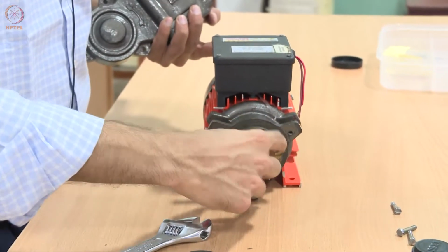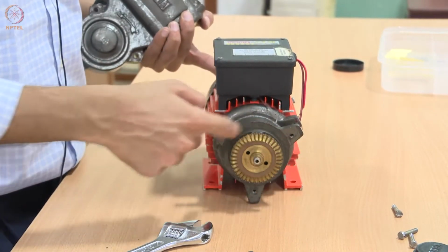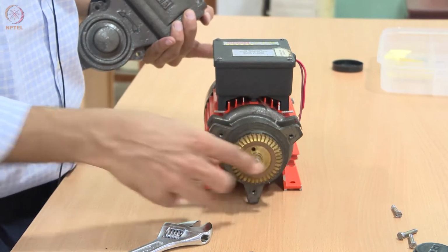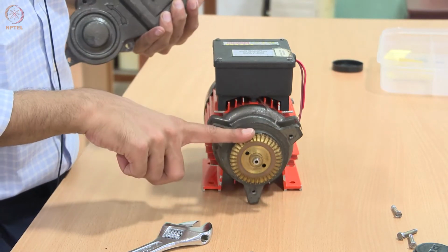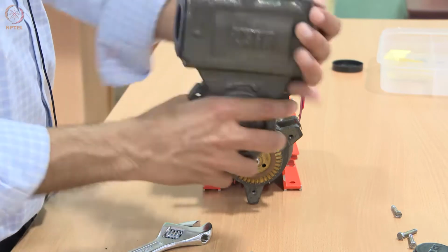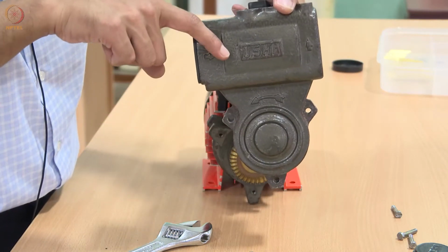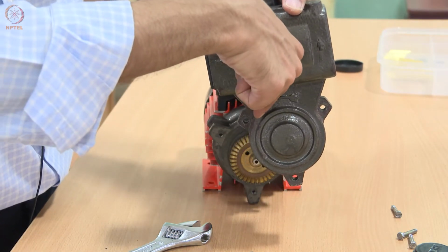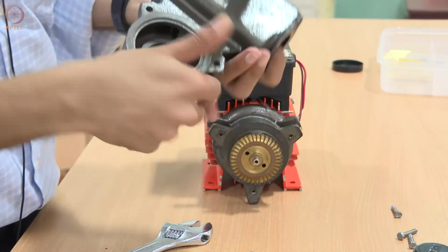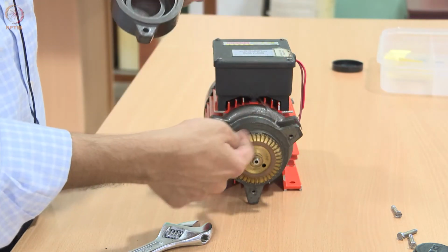The impeller rotates counterclockwise. So this is a special impeller. These impellers you will only find in self-priming pumps. Okay, so water enters this way. It basically enters tangentially here, right? So the impeller carries the water.